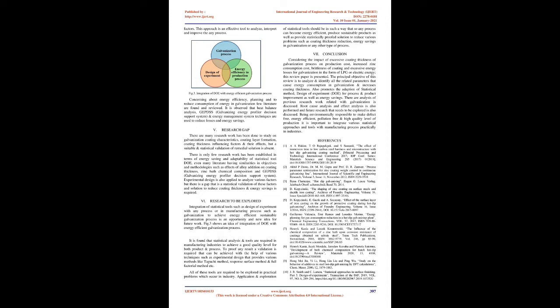These causes come from many sources that are discussed below. Zinc pot. From examining literature, it is identified that the major cause of zinc thickness originates from the zinc pot, also called zinc bath. The influencing factors are zinc bath temperature, immersion time, alloy addition, and zinc bath chemistry, etc. Various literature work has been studied in the review section regarding alloy addition, zinc bath chemistry and their effects.